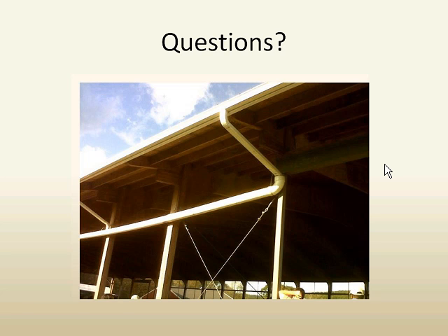Okay. And next question now, I'm going to paraphrase all this. It's from Punya. He had a good question. He said, you talk about gutter and downspouts, but how do you calculate how much water is collected on top of the roof structure? I reply with my rule of thumb that I always use, and that is, for an inch of rain on 1,000 square feet of surface, you get about 600 gallons.